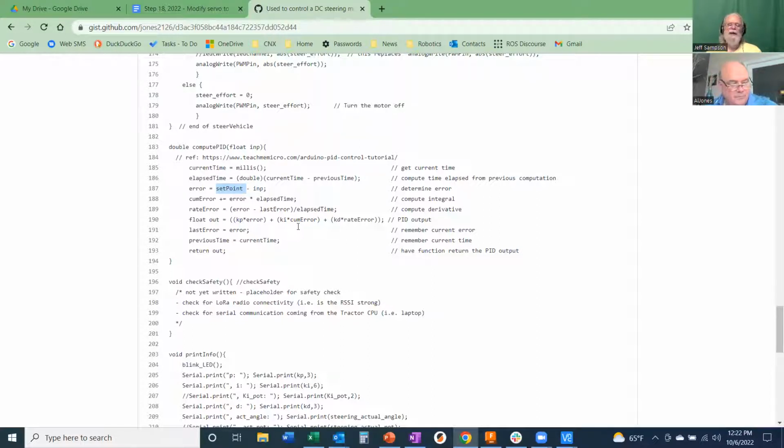It's going to provide an angle, and as I've mentioned multiple times, I don't know if that's the angle of your front wheels or that's the angle we want the vehicle to turn as it drives forward. And I can't find anywhere to tell me which is actually correct on that. But the answer is yes. ROS, the way you got your TEB planner set up, where you said set the flag to give me an angle instead of rotational velocity, yes, it will just hand you an angle and then you deal with that.